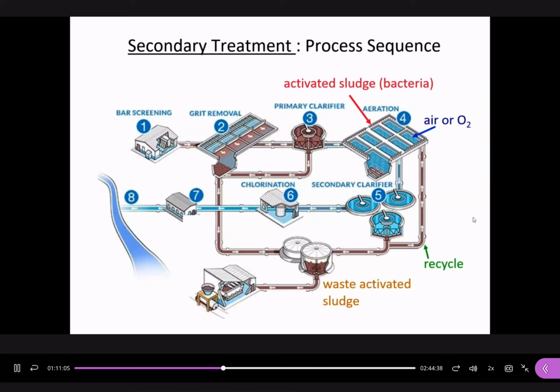Imagine you have this aeration tank. You have wastewater coming in all the time, right? If there is no waste or no removal of cells, the cell concentration will continue to increase because you are supplying food continuously, right? The microorganisms will grow forever. Of course, here we do not talk about the limitation of the tank. Therefore, we have to remove them. We need to maintain a constant concentration in this aeration tank. The secondary clarifier is to remove the extra cells.